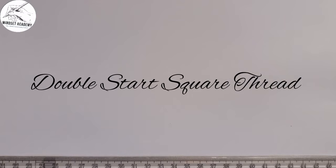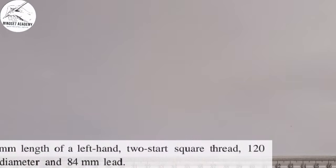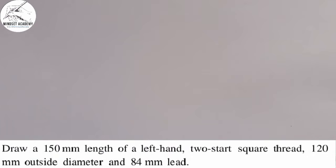In this video, we want to learn how to construct a two-start square thread. And the question goes like this. It says, draw a 150 millimeter length of a left-hand two-start square thread, 120 millimeter outside diameter, and 84 millimeter pitch. Now, first thing we have to do is just write out the parameters because we realize we have some unknowns.